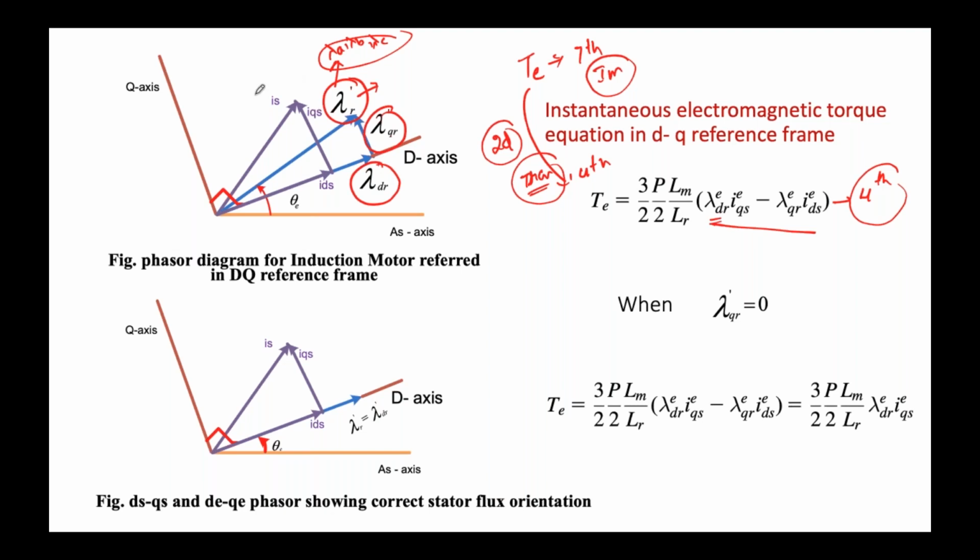Similarly, the resultant stator current, the actual current vector, we can realize by using two-phase components also. Whatever information you get from three-phase variables, you will get the same from two-phase variables. Similarly, stator current also we can realize by taking two-phase D-axis and Q-axis current.